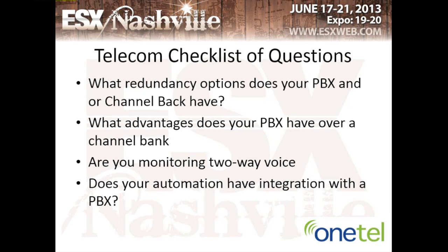Look at the advantages of a PBX over a channel bank as well. The big one is if you're monitoring two-way voice. Depending on the automation you're using, it's going to be a lot easier to use a PBX than a channel bank. Most channel banks don't support hook flash and transfer. That's where a PBX comes into play for your two-way audio. And does your automation have integration with the PBX? A lot of the automation companies today are integrating with PBXs. The great thing there is you can do all kinds of things like caller ID injection, so when a call comes in, it pulls up the customer record right away so the operator knows who they're talking to, and that kind of stuff.